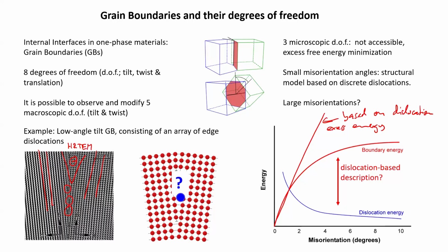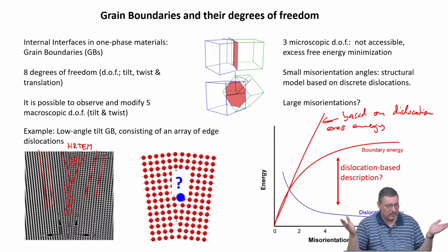Like if my grains have twins also. Yes. I am calculating my misorientation through EBSD. Yes. That gives some misorientation, which includes this twin boundary also. Yes. Can I correlate with energy of dislocation, like if I want to say No. Overall? No, because the twin boundary is a boundary that is very special. It has much lower excess energy, so it's almost zero, because if it's a perfect coherent twin boundary,